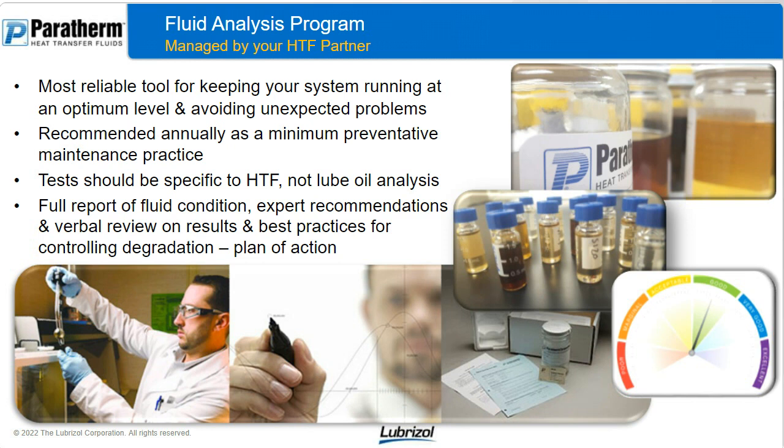So that's a super user tip. And I know it's a basic one, but it's one that I'd say I wish 100% of all users did, a strict fluid analysis program, but unfortunately it's probably more like 25%. And it's something so easy and something so useful that if you really appreciate the impact of your thermal fluid system, having a regular fluid analysis program is going to be important. So what are we testing for?